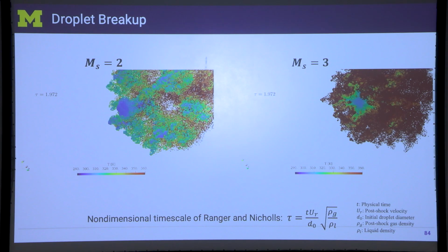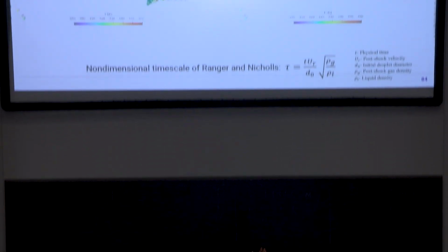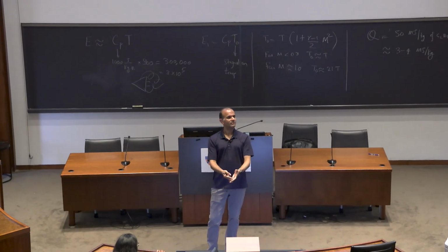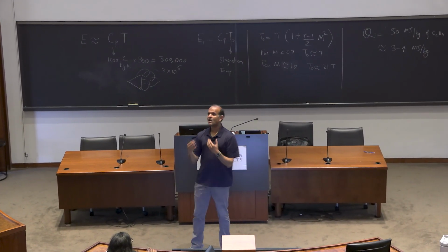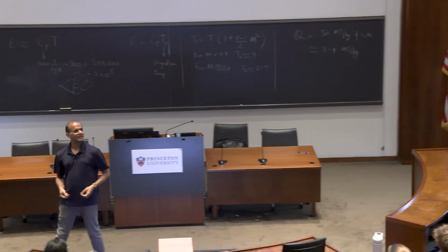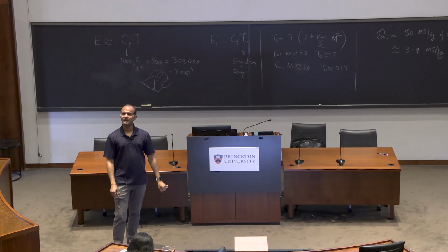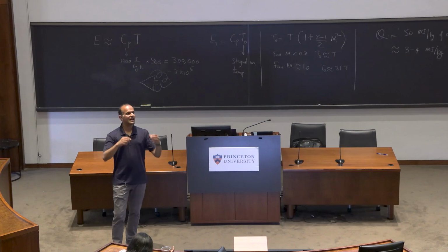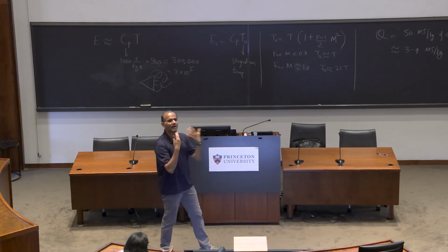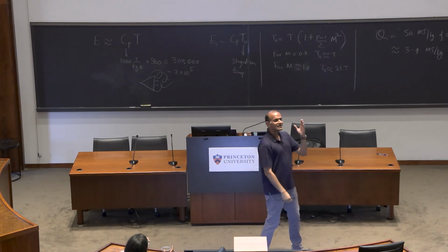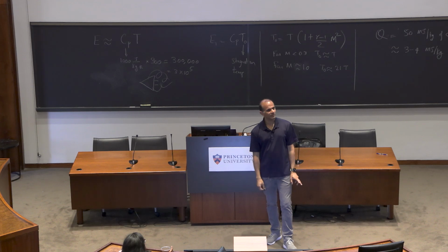And as it shatters, it distributes itself widely. So initially the droplet is sitting in 20 micron space. It shatters itself and distributes in about a millimeter box. So the shock not only affects the evaporation time, it also distributes the fuel air mass behind it. So now at those locations, evaporation can be much faster. Now there is hope that there could be evaporation.